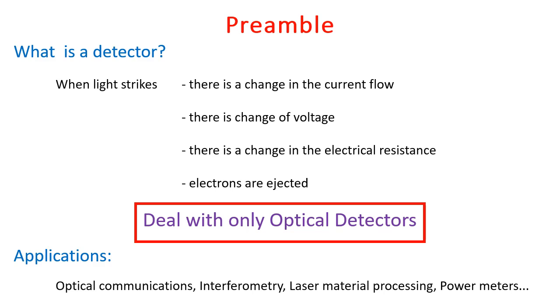There could also be a change in voltage, and you are familiar with detectors of this kind, which could be, for example, a photodiode, which is a PN junction wherein the number of carriers are changed as the light strikes on that piece of PN junction, and hence when it's connected to an external voltage, there is an electrical change in terms of either current or voltage.